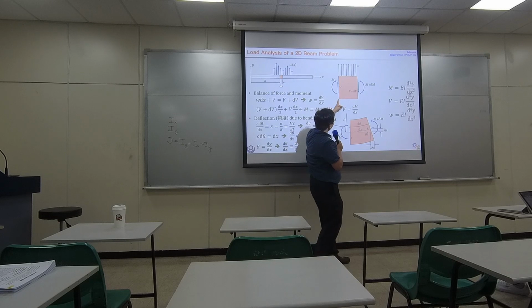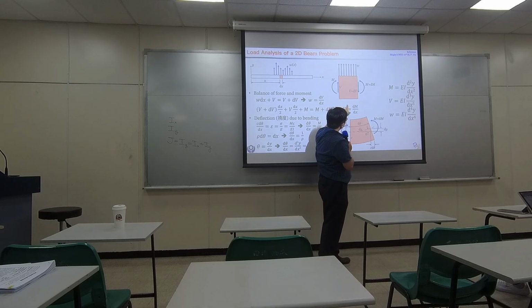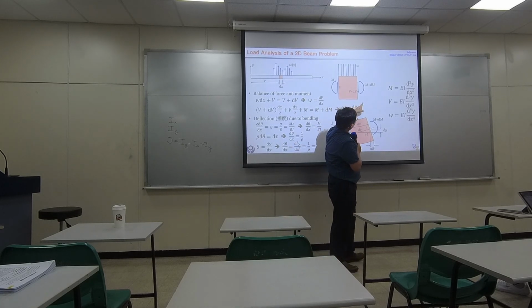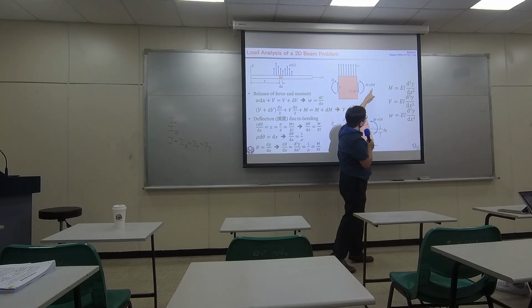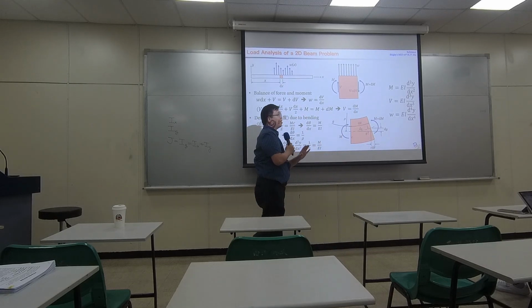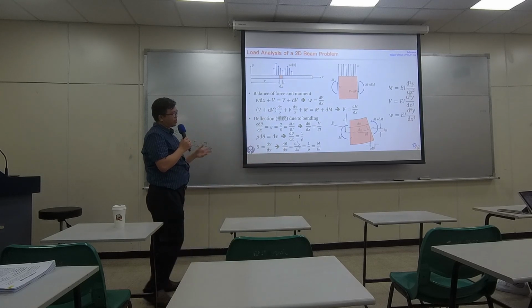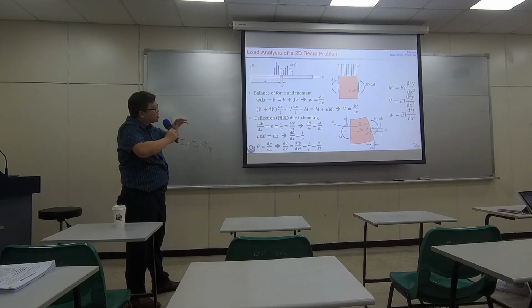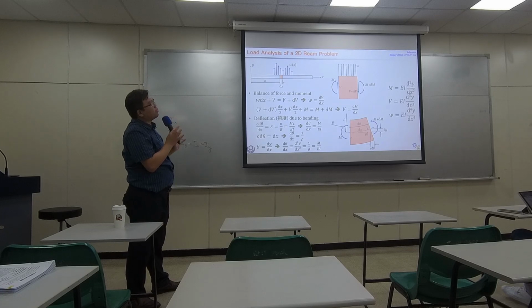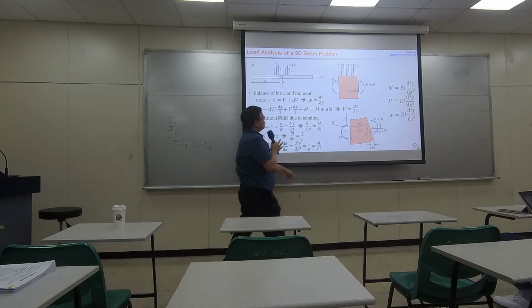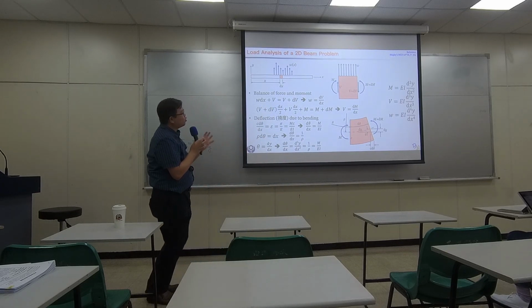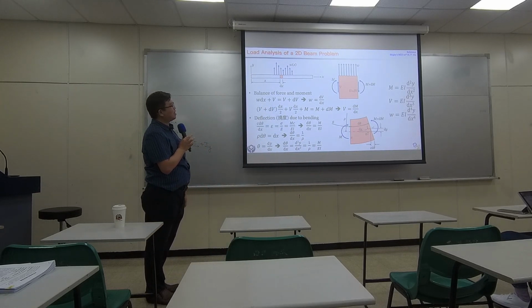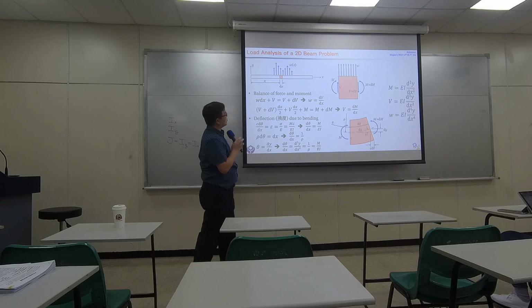So when I move toward the right by dx, shearing force and bending moment increase by dV and dM. They could be positive, zero, or negative. Just to define some symbol over there to show shear and moment could be changing. Once you have that, then the rest are just derivations.